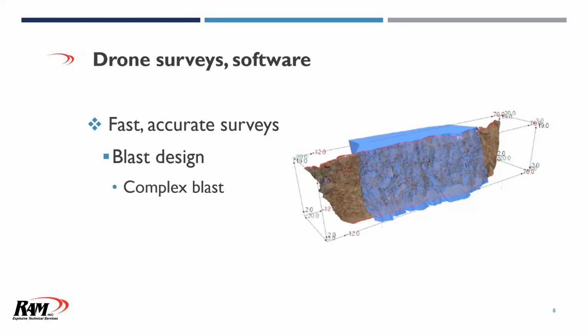So it may be, you could have a staggered pattern, square pattern, rectangular patterns, whatever it is. It may have a multitude of angle holes in it, whether certain areas, certain rows, corners, whatever the case may be. Even three-sided shots now can be managed in the software to be able to handle those types of complex designs. But again, the critical thing is we're generating this minimum burden profile.